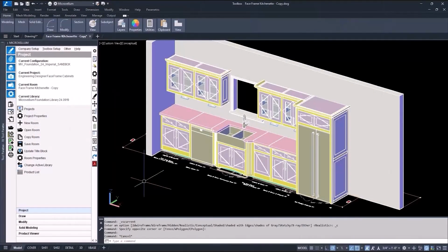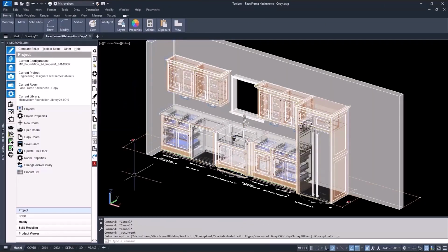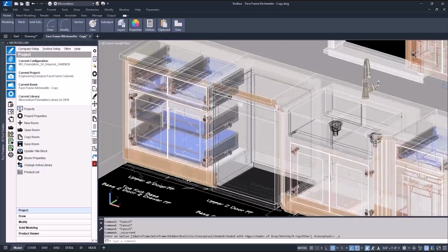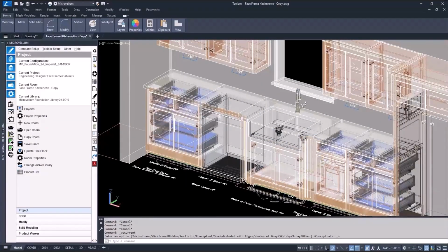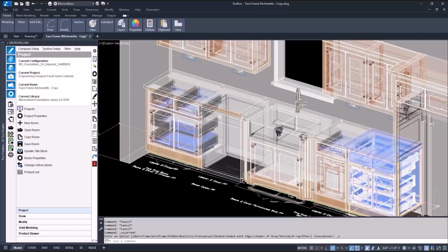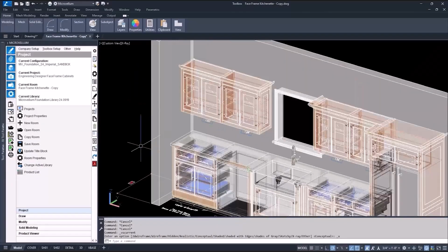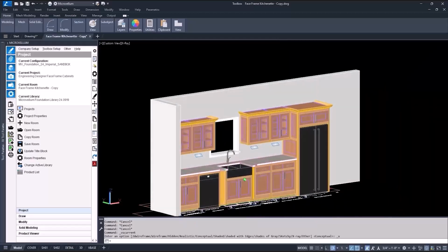So if you watched the style and rail modifier video, then this should look familiar. This is the small kitchen I'm getting ready to process. I got some rollouts in the base cabinets, the farmhouse sink cabinet with the frame modifiers, and all these cabinets have the Microvellum MDF profile doors. With the uppers, I have the glass door prompt turned on, and inset panels at the applied face frame ends.